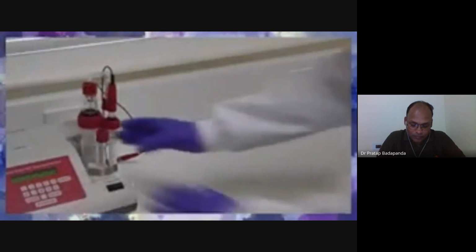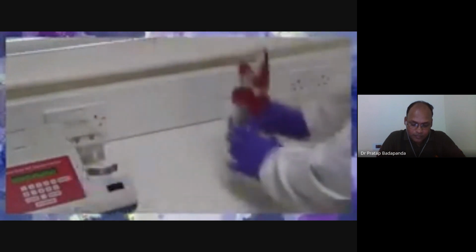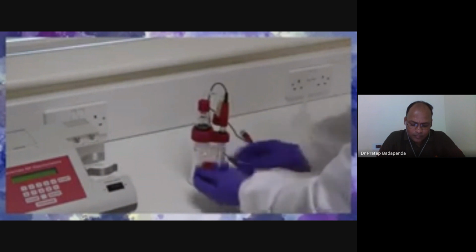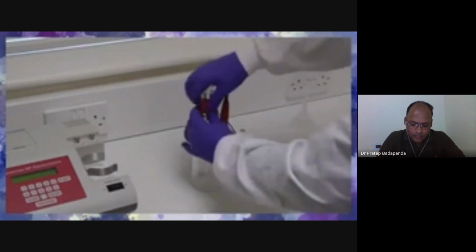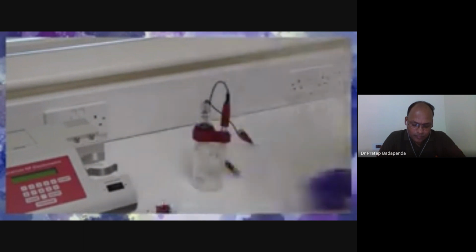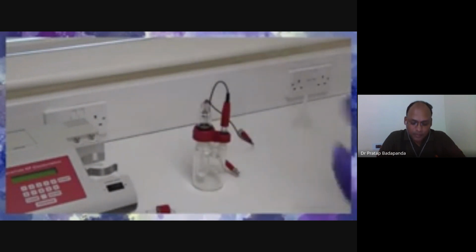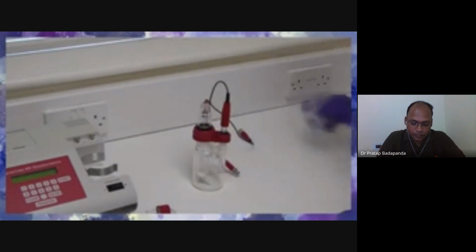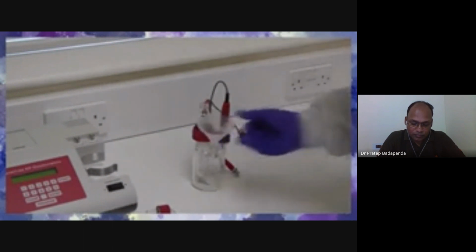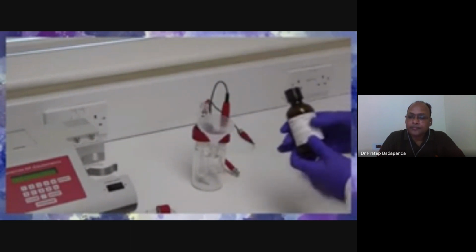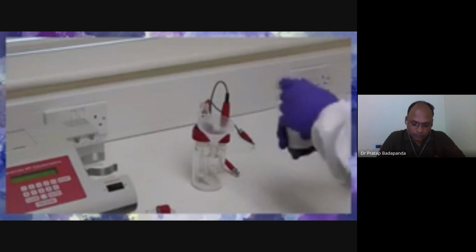Before adding the chemicals, remove the assembled glassware to avoid spillage on the Aquamax KF moisture meter. Remove the injection port and the drying tube and insert the stirrer bar. Add the full 100 milliliter bottle of reagent using the supplied funnel and reconnect the injection septum.